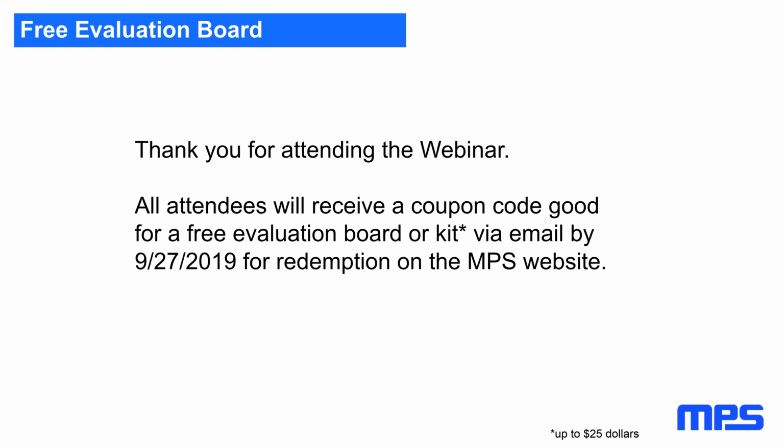On the low frequency, it's easier. So below 5 megahertz, SPICE actually works, because the parasitics are not that high. So there you can, with normal simulation or just a sheet of paper and calculation of the filter, get the results you can also measure. So there you just have to hire the components.